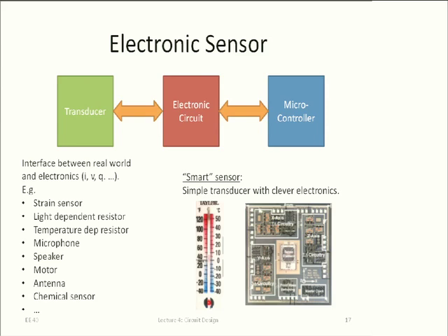And here are a few samples of these sensors. In particular, you will sometimes read about something called a smart sensor. A smart sensor is probably not really smart in the sense that we hopefully are smart, right? But the idea is that it takes a sensing concept like that, and then it adds electronics around it to take care of all the things, like if it's nonlinear, it takes care of that. It has an offset, it takes care of that. So this is one of these sensors, a 3-axis accelerometer that we built in my group, and there is lots of electronics around it that figures out what's really going on inside, and it actually produces already a digital output ready for the microcontroller to work with.